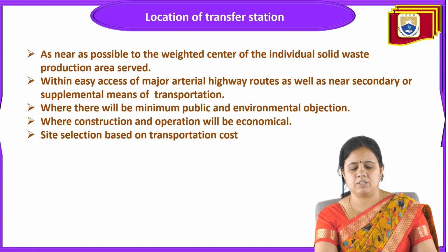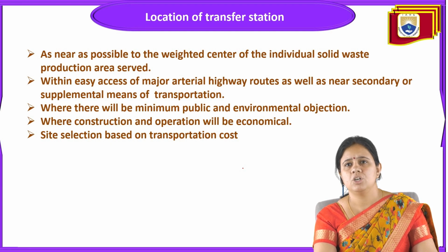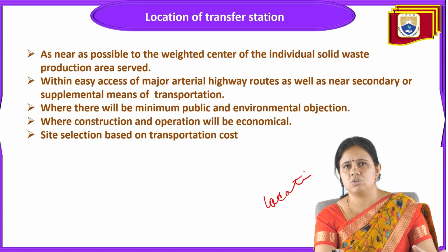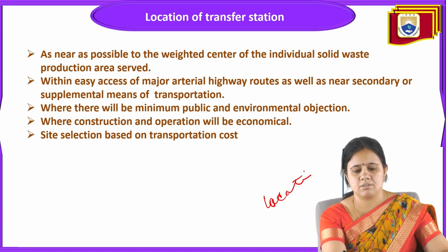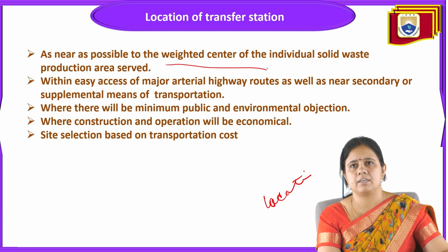Next, location of the transfer station. Location is also very important, and these are the points that should be followed for selecting the location. So what is the first point? It should be nearby to the weighted center of the individual solid waste production areas served. It should be as near as possible to the weighted center.